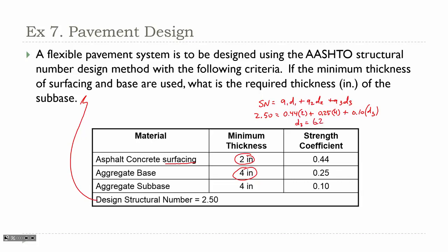D3, we get 6.2 inches, and since it's a subbase with large aggregate, we would round that up to 7 inches.